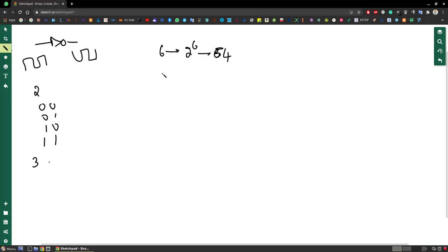In one simulation run you should be able to evaluate the schematic for all possible input combinations and see the output. You should not be providing some input data, like all 0s, running the simulation and then seeing the output. That should not be the case. In one simulation run you should be able to provide all the input combinations, and the corresponding output waveform should be present.